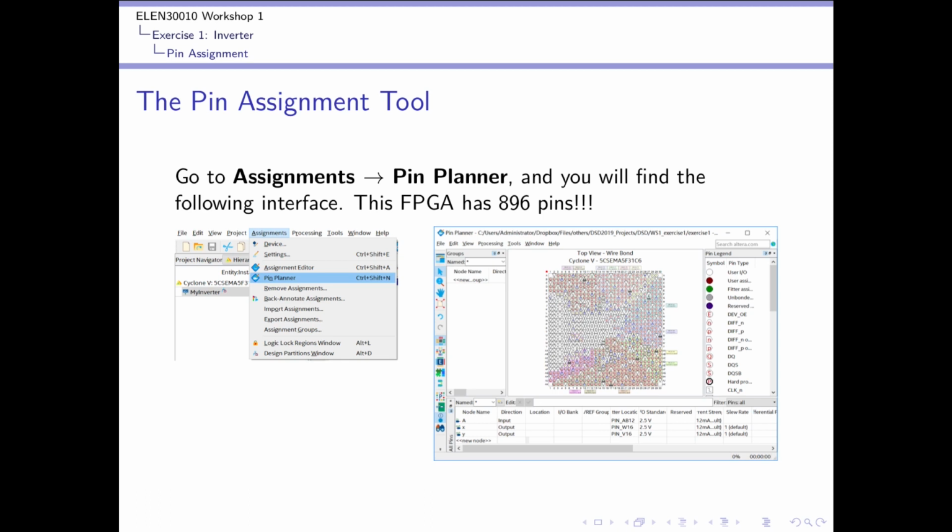If we want a push button connected to this pin here, we can't change that. The developer of the board hardwired that in. If we want the push button to connect to our digital circuit, we first of all work out what pin it's connected to, and then connect that pin to the input that we want it to be connected to of our hardware design.